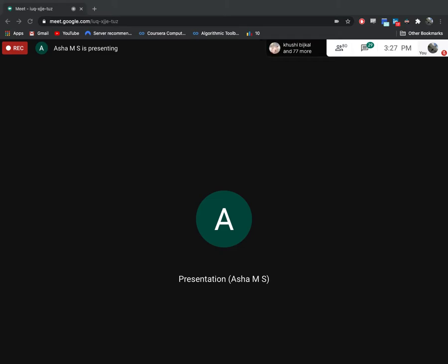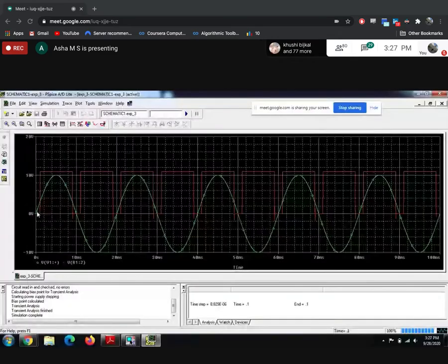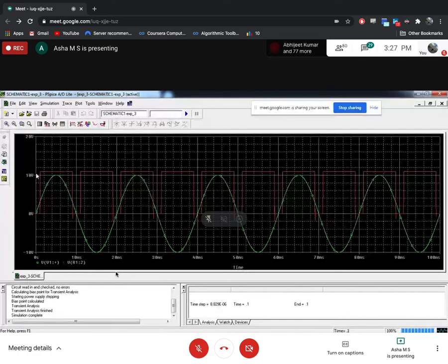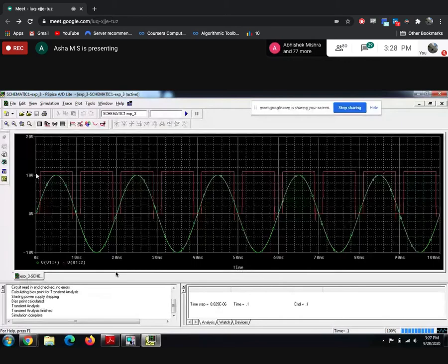Here the origin is set to 0. The peak to peak voltage we have given is 10, so with 5 subdivisions, each subdivision takes 2 volts. So the first division is 2, and we have taken 3.